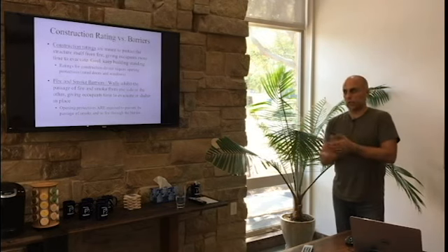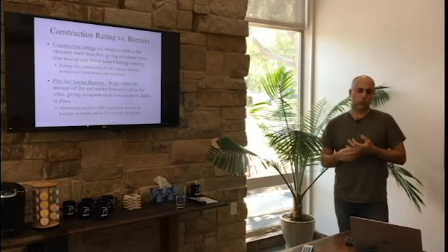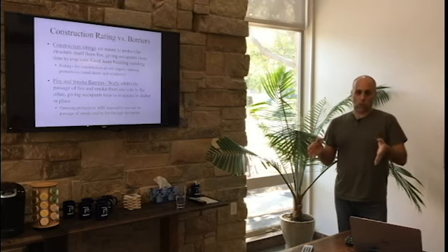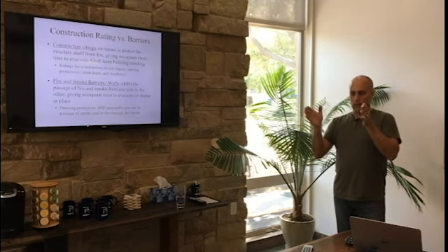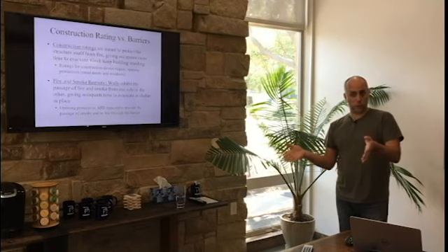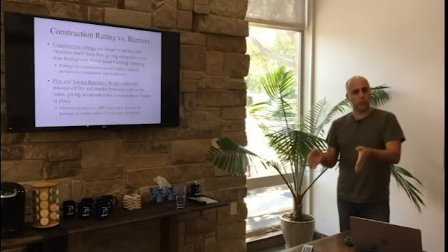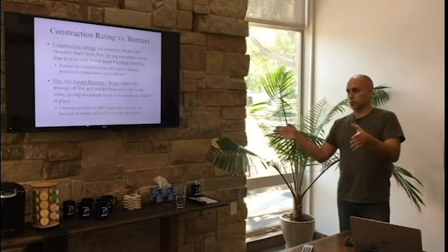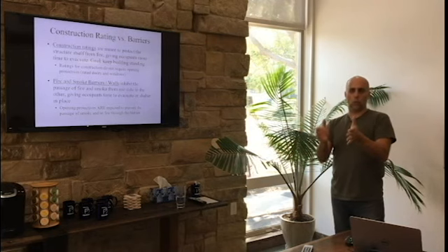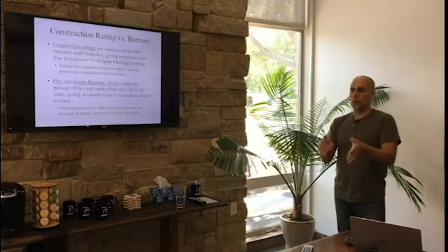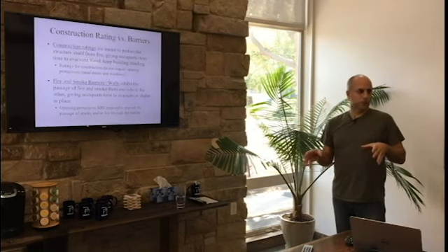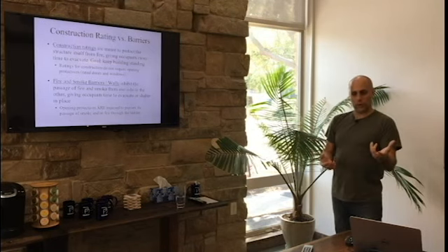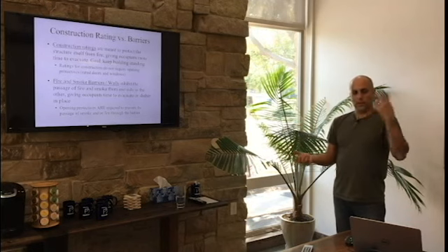When I did a lot of educational work, elementary, middle, and high schools in the state of Florida, we would do tilt wall construction. At the time, we were required to have 3-hour rated exterior bearing walls for the type of construction we were doing. And it was a mixture of concrete tilt wall exterior panels with a steel frame on the inside. So the steel frame is bearing on a 7 1/4 inch thick concrete slab. Well, those were 3-hour rated bearing walls, but the corridors were 1 hour rated. So the drawing said 3-hour construction and 1 hour bearing walls. And then the doors were 45 minutes because it was a 1 hour corridor.